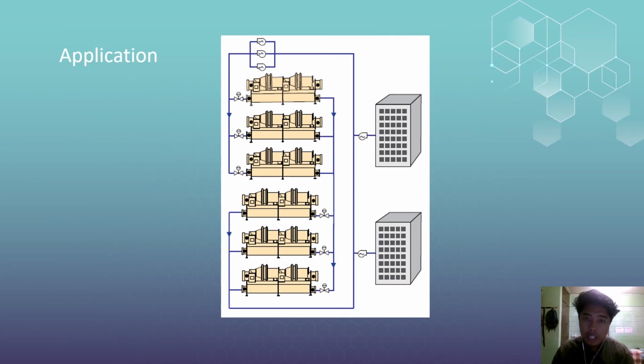plan. If the initial plan is built to accommodate many future buildings or load, the early challenge is operating the system efficiently with much lower loads than it will experience when the project is complete. The system may need to blend parallel and series configuration to accommodate the wide range of load and plant experience during phased construction.